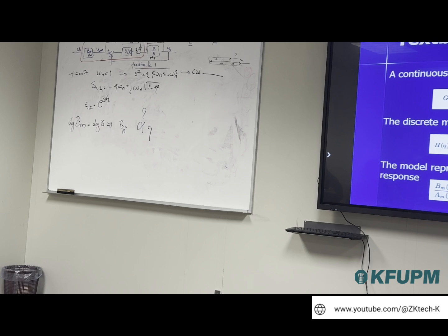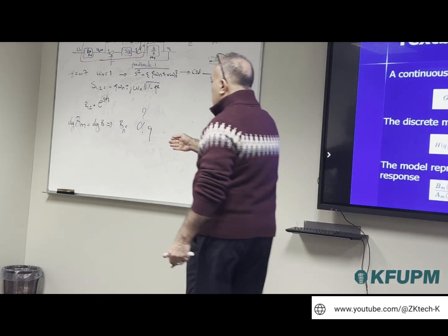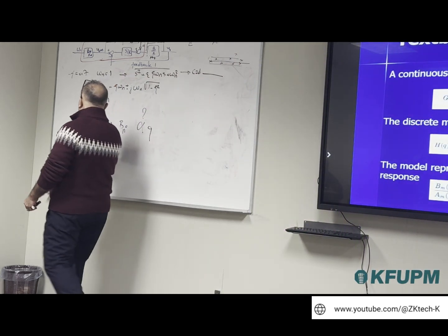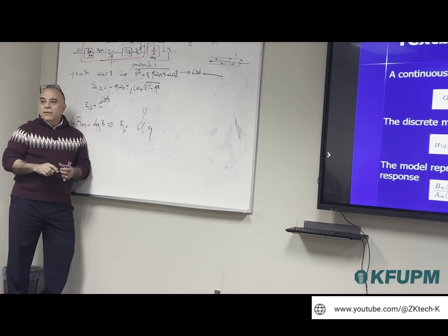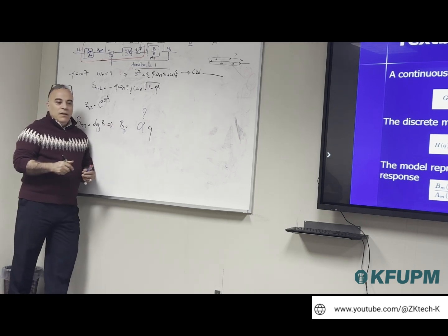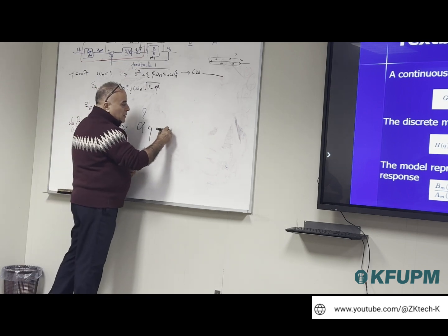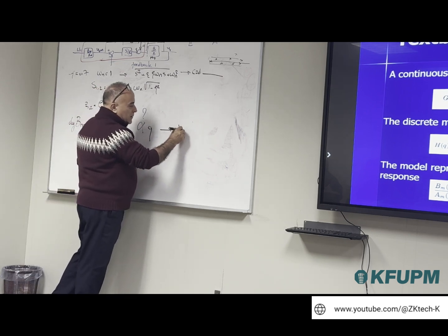We calculate from omega and zeta. Sometimes when you do the pole placement, you have some steady state error. So we need to calculate this alpha based on the error, that is 1 over the DC gain. This is your reference model. So what steady state error do you want to see in your reference model? 0. So alpha will be computed from the steady state requirement.